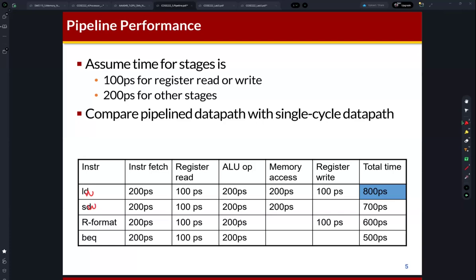Okay, so in order to design a pipeline processor, we need to balance the delay of each stage, so each step. It is because the critical delay determines the clock period. And why is the clock period critical? Why is it important? It's because of this equation, right?